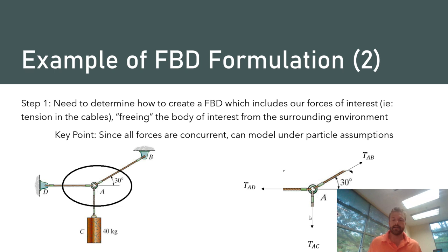So what that means practically is that when we draw our free body diagram, we want to be sure to identify as many knowns as possible. Since the forces in the free body diagram are vectors, those knowns involve both the magnitude of the vectors along with the direction. So we want to capture any of that information we can. In addition, reflecting back on the first portion of our lecture for Chapter 3, we want to build in any physical intuition that we can as well. What do I mean by that? Well, remember that the forces that are supplied by a cable to a body are directed along the axis of that cable.